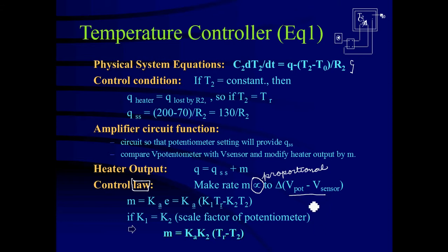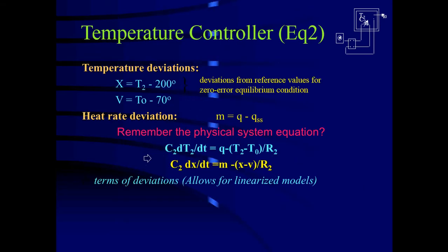So this is called proportional control, obviously, because the more error that we have, the more correction that we make, or the less correction that we make. So that is called proportional control, and then we express it in this function like this. Very good.